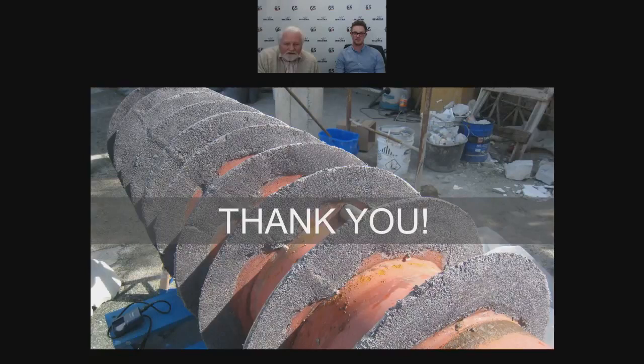And the problem there is, if you've got hard face welding on there, number one, it's extremely difficult to get the surface profile, the minimum 75 microns that we require to get good adhesion. And number two, any relatively thinly applied epoxy coating applied in that area, right on the edge, will not perform as well as hard face welding. That's because, dependent on the clearance between the edge of the vane and the container inside which the vane is running, there will be friction, and that friction will generate heat. As the edge of the blade gets hotter, of course, the material becomes softer. So generally speaking, on the edges of the vanes, stay with hard face welding. It's about the best option. But on the flanks of the vanes and the shaft itself, Belzona can give you extremely good service.